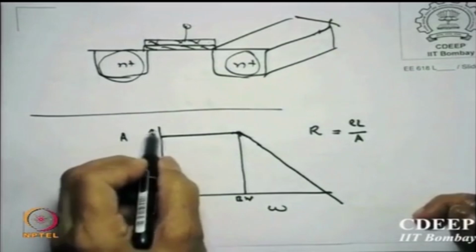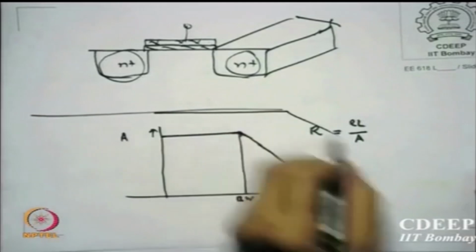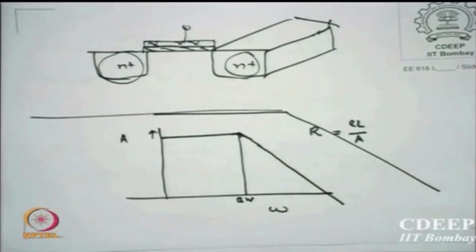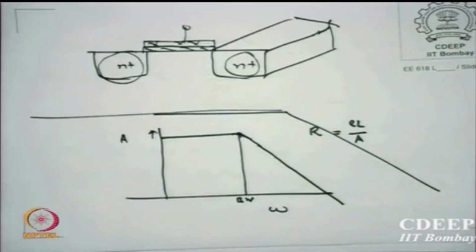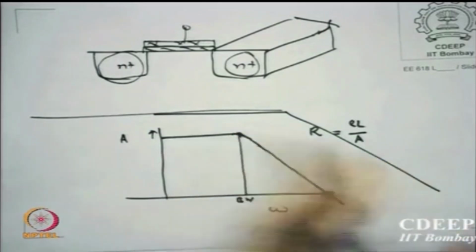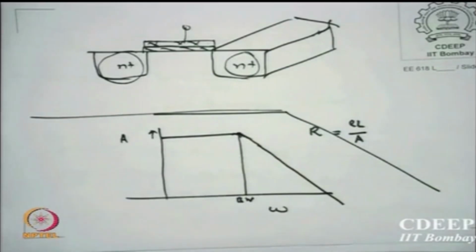Now few things I must know. I want to increase this A, that means I am really looking for something like this in real life. I want larger gain, larger bandwidth, and also in turn power should not go up. That is what I am asking myself, and then I will say, "Arey baba, itna nahi, kuch do mujhe." Then I will say what I can actually work with, so that the third parameter may help me to get what I want. So 2 I can get, maybe third I will have to give up. So within a given range, if I can fit that, then I say I have designed an amplifier. Is that okay? So my worries are bandwidth, gain.